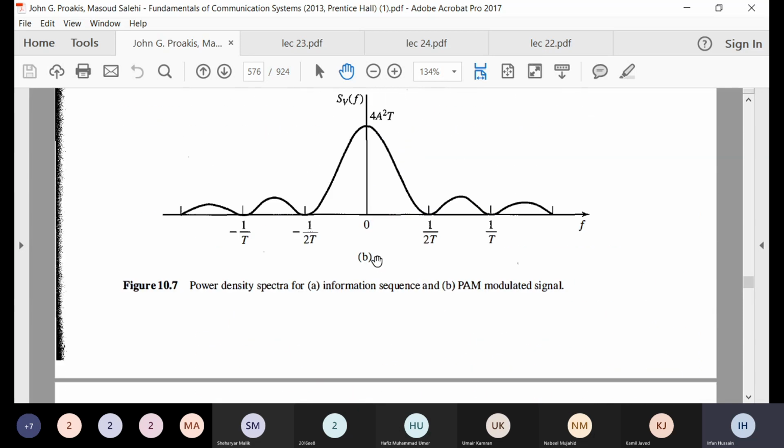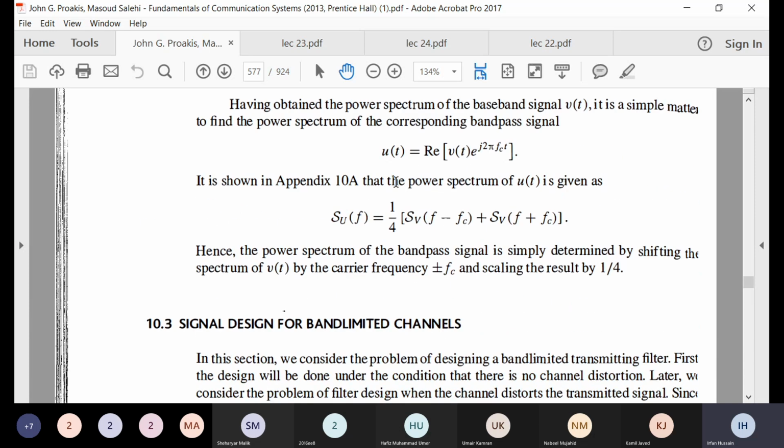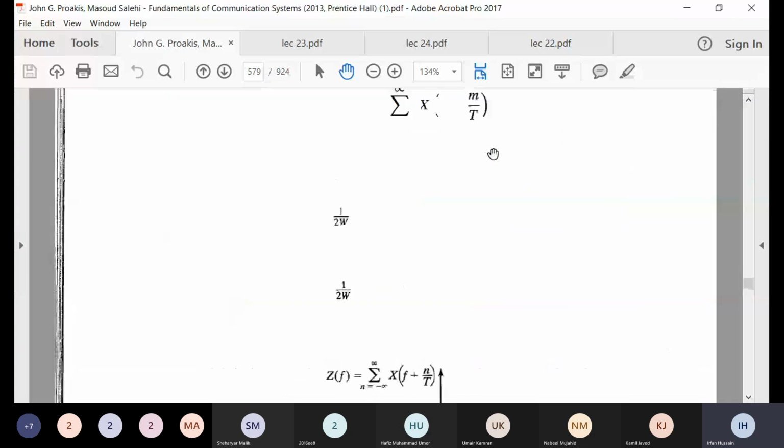अच्छा, so you can see this is your SVF, but this is SVF for baseband. If I want to write this for passband, so you can see what is the passband. So passband signal is the baseband signal, ठीक है, times e^{jωt} and then taking its real part। ठीक है, here we know the baseband signal is totally real। ठीक है, जैसे हमने देखा था यहाँ पे तो कोई चक्कर ही नहीं था, सारे EM सिम्बल्स आपके रियल हैं, GT भी आपका रियल, हर चीज़ रियल है। तो इसका ये हमने पहले ही देखा हुआ कि एक्चुअली ये क्या होता है, मगर इसने अपेंडिक्स में किया हुआ भी है, आप चाहें तो वहाँ से देख लें।